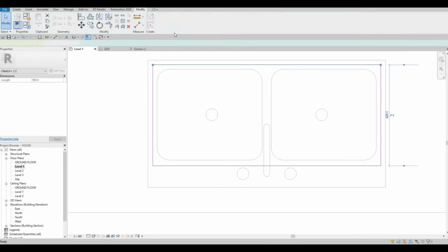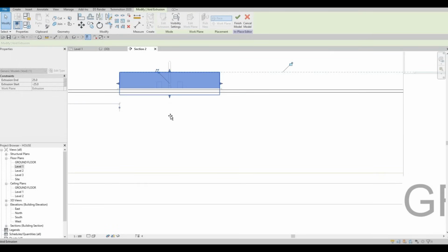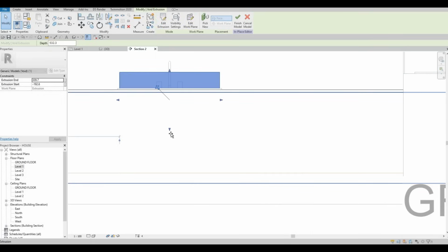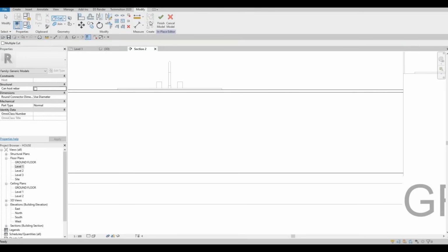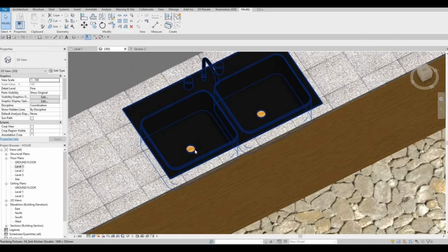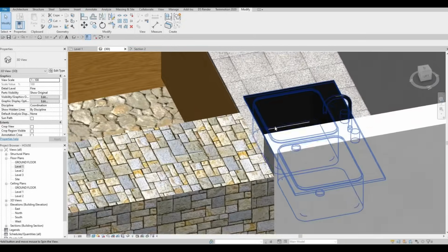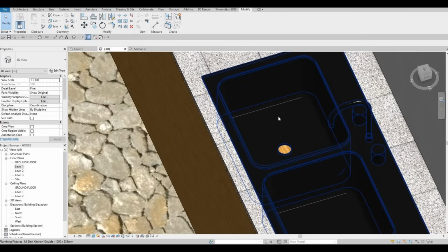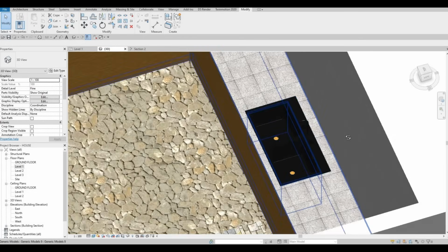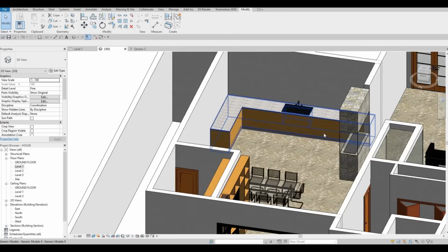And then after that, click on finish, go to our section so that we could extrude it. We could extrude it from the top and then from the bottom. We could pull it all the way to here. I know it's just roughly like here, but that's good enough for me. And then we could just click on cut and then click on finish. If we check it, as you can see, we can see the bottom now. So that's how you're gonna see it if you successfully create the void extrusion from here. So now this one's good.